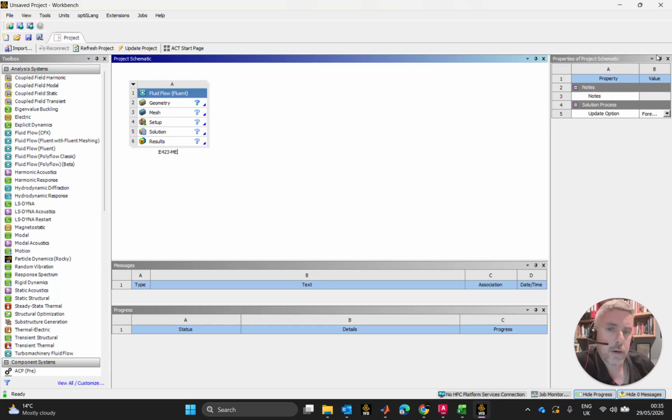Now, if you are doing a parametric study and you are changing the physics of the flow for the most part, or the physics of the discretized space independent of geometry, so if you're changing the amount of elements, or from a solver point of view changing inlet velocities, or changing temperatures at boundaries and so on, then absolutely go with the best CAD package that Ansys gives you here.